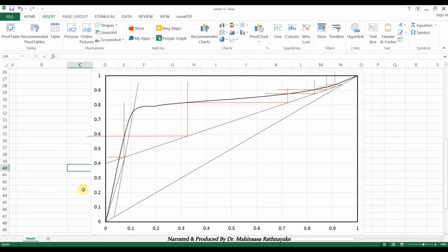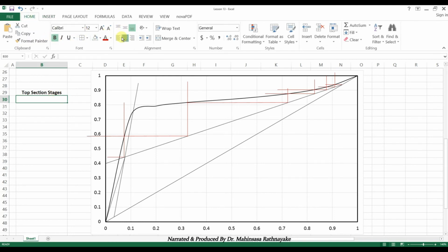You can see the stepping off in the top section. If we draw this manually, drawing the stepping off lines above y is equal to 0.8 must be done in a larger scale diagram. So the manual method has to draw many diagrams in larger scale, and the possibility of mistakes and errors is high. We can see that a total of 7 stages are required above the feed.